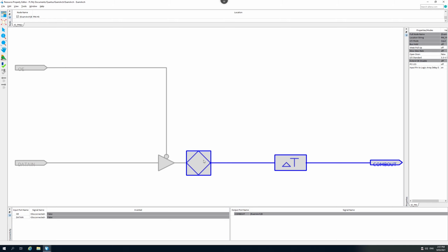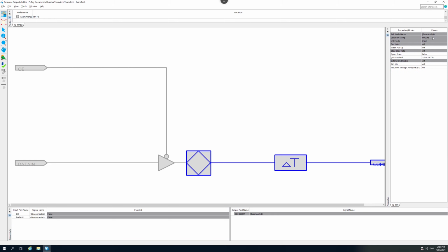Now this diagram doesn't show the additional processing. To see that, you can have a look at the Max2 user manual where it describes the architecture. That document is in the lecture notes included as a PDF. We have a look up here at the full node name. We see that it's pin B here. The location string is the exact pin number this is. It's being configured not as an output but as an input. So the signal comes in the pin, then through this time delay we'll talk about in a second, and then to the FPGA board itself.